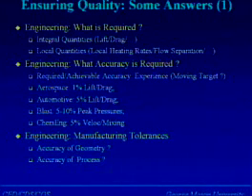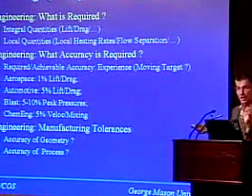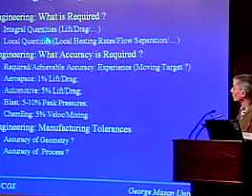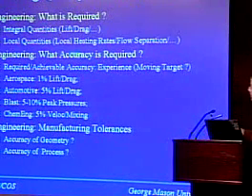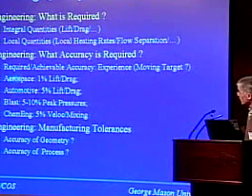But for many people, local quantities are important, and not just any local quantities, but a local quantity at a certain particular place. So there is no universally perfect mesh. If I want to have lift and drag, I may need a very different mesh, and I may have a very different sensitivity to input or physical parameters than if I want to have a local quantity at a certain point. What is the accuracy that is required? Well, I've listed a couple of sectors here.